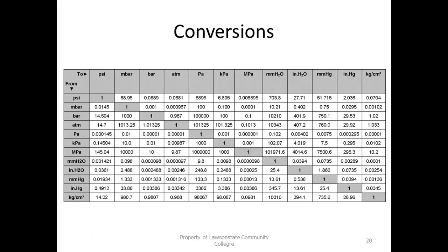So that's why when we use pressure, we use kilopascals all the time, because if I went from 100 psi over to pascals, then I'm going to take 100 and multiply it by 6,895, and that's going to be a real big number. But if we do it in kilopascals or megapascals, so megapascals, we take the number and move it over 6 times, right? You understand? And then kilopascals, we would take the number and move it over 3 times. So pascals is a very, very often used measurement of pressure.